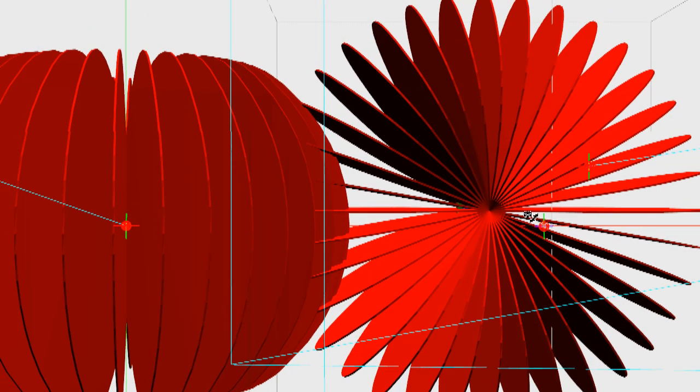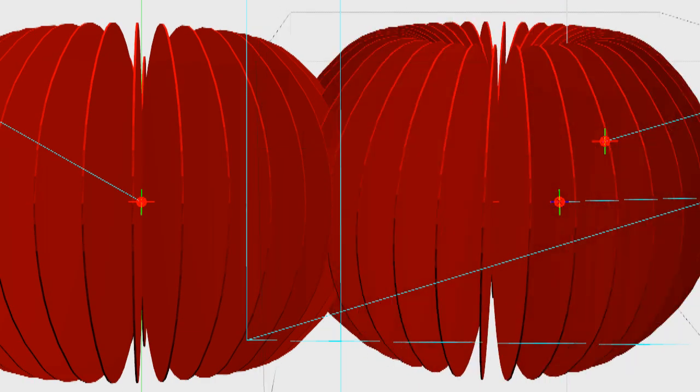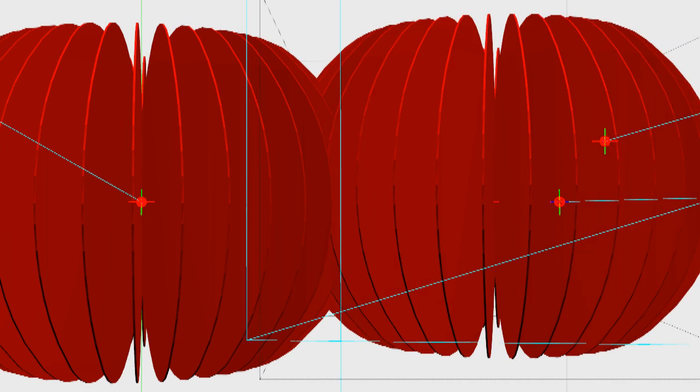This mismatch will cost us about 26 decibel of gain loss, which is significant, yeah? And what you'll notice is that here, this is our cross-sectional area that's matching up, yeah? And if you were to measure this wafer-thin cross-sectional area, plus this bit, plus this bit, plus a little bit here, a little bit there, it's tiny in comparison to how it is when these two are matched up in their orientation.